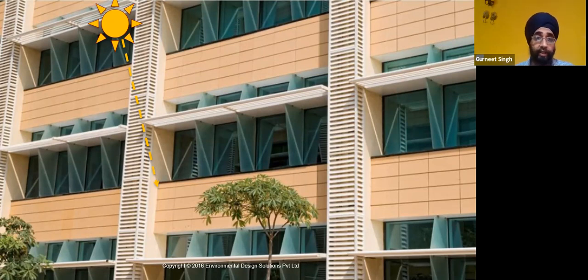The second one is they also specify that they want at least 100% of their space to be well daylit. And the third one is in terms of heat gain. They say that you need to design your facade, or the specs of your facade, glass, and the wall, so that the peak ingress heat load from the envelope is not above a certain threshold.